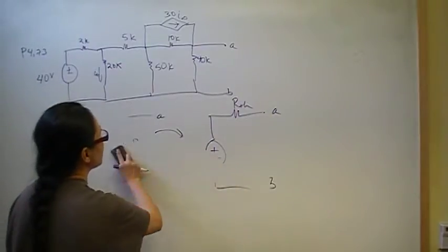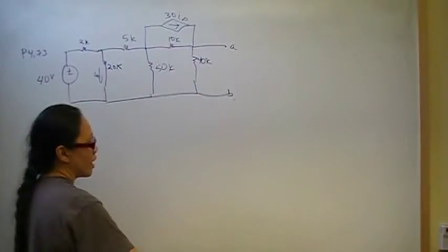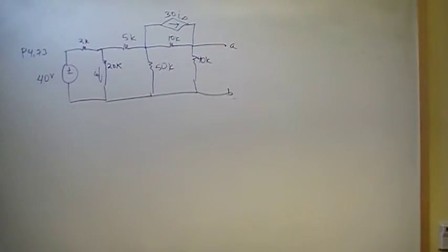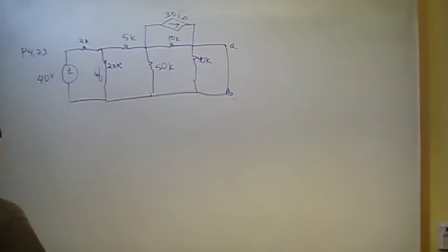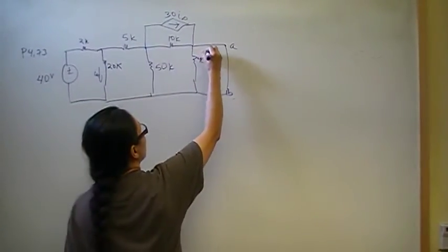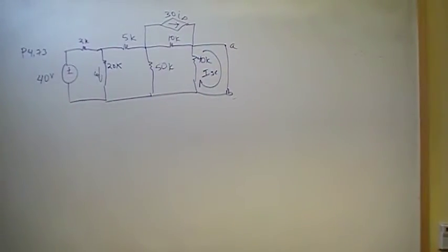Your primary tools in doing this are mesh analysis, KVL and KCL. So you have a choice, and what I went with in finding the Norton equivalent circuit is the mesh method, because I just like it better. Everybody has their thing, and that's my thing. So I went ahead and shorted the load, and then I decided that I would find the Norton equivalent circuit by finding this I short circuit, and that would be the first part of the problem. So let's go ahead and do that.